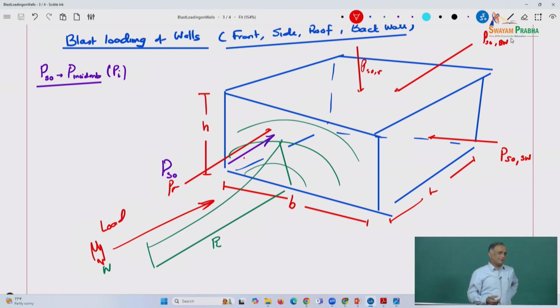And in practical applications, we've tried this with bridges. We've used a standard bridge design software, and those are all static loads, but we have converted these loads into pressures in this manner and applied them, and of course it is much higher, as some kind of a static load. You could add factors. I don't know if there's a whole lot of research, like you have an impact factor in bridges due to dynamic loads. Those are some things that you'll have to account for.